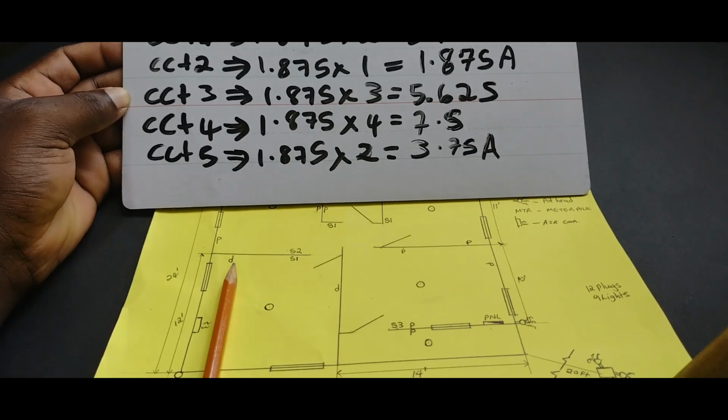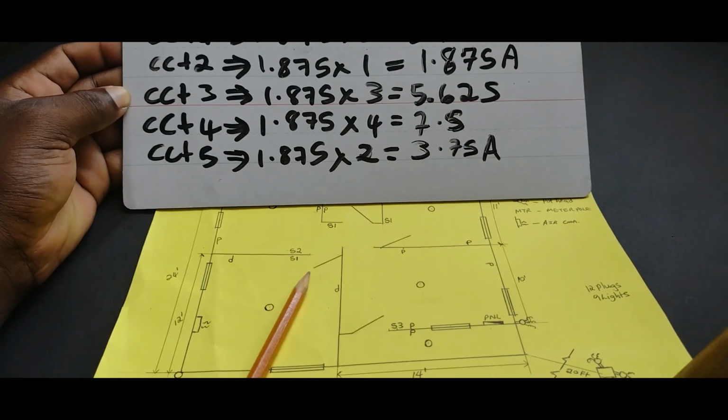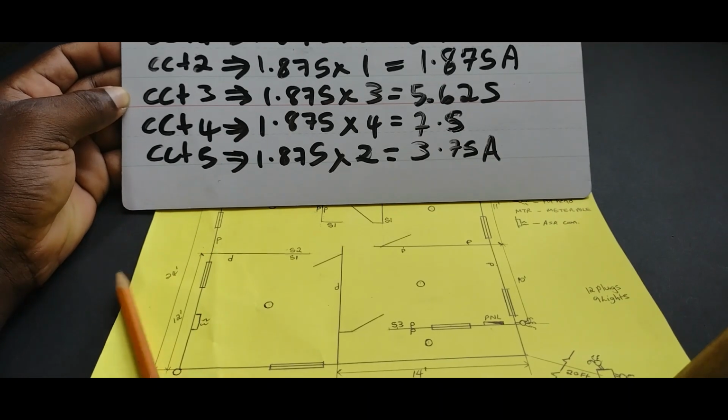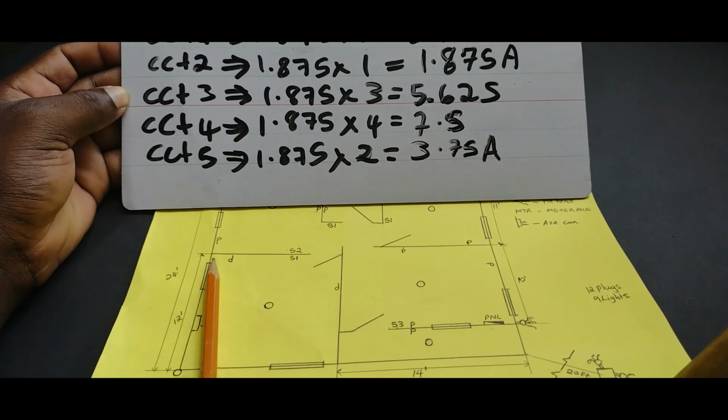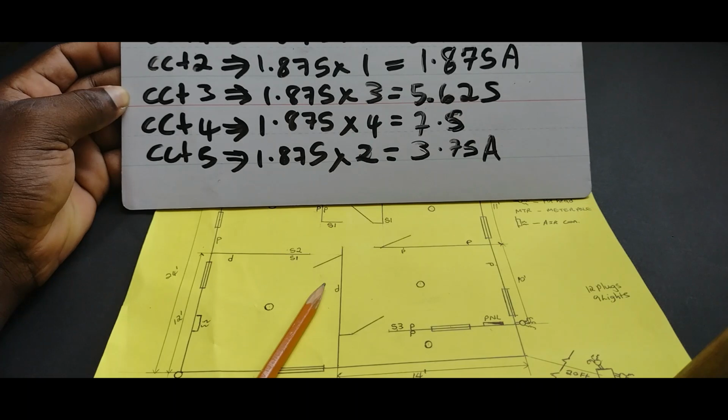We normally put a max of 4 on them, and later on, if there are any additions, 1 can go on, and we won't be running the breakers at max. Now in this case, we have 1, 2, 3 on that circuit breaker, and they are in the same general area. So if you switch that breaker off, 1, 2, 3 will go out.